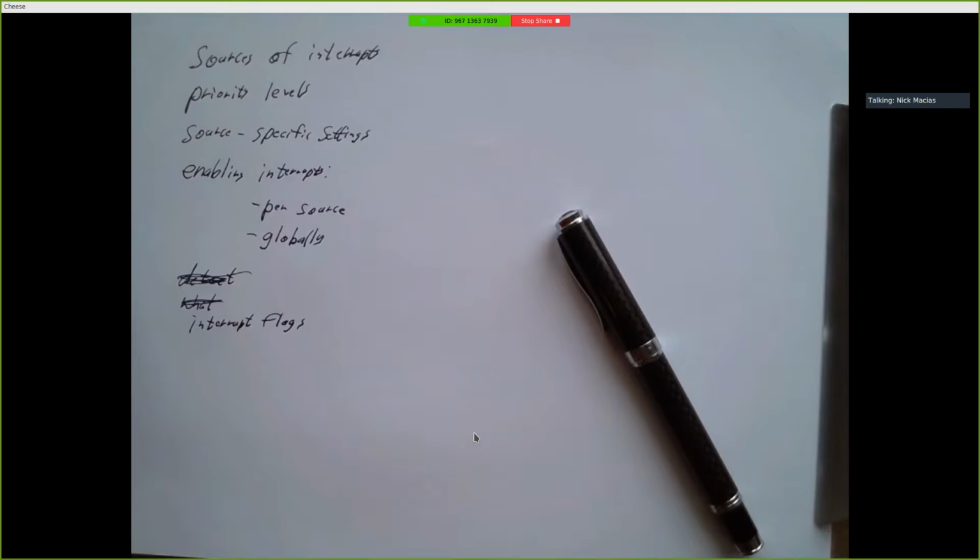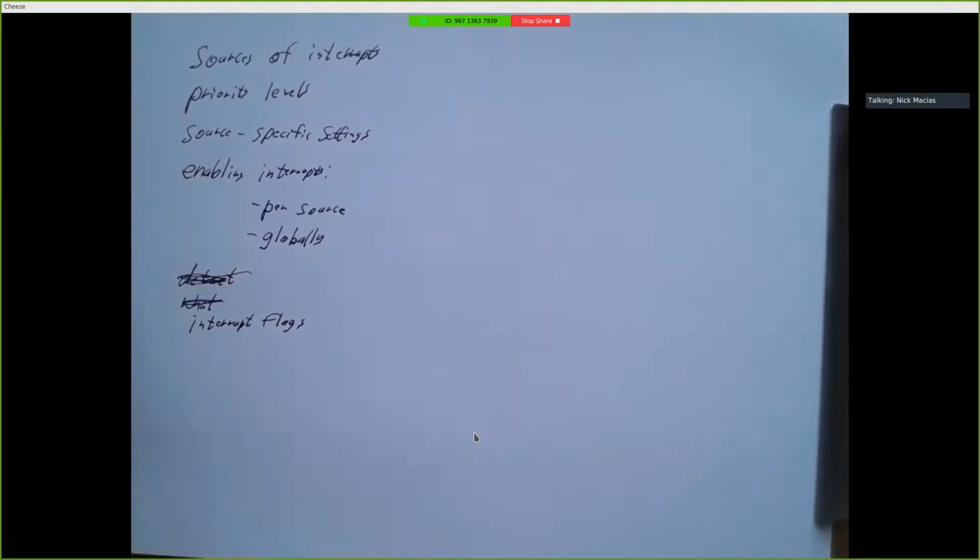So we don't have a doorbell and a cell phone alarm and a smoke alarm and a window and a flashing light and all this other stuff. We basically just have interrupt, right? Or maybe interrupt, right? We have two levels of alert. And when we get that alert, we know something interrupted us, but we have to figure out what it was. If we've enabled 5 different things that could all generate an interrupt, we have to figure out which thing caused that interrupt. So there's flags associated with each possible interrupt.